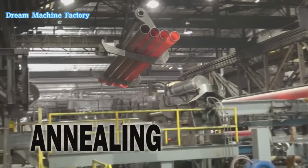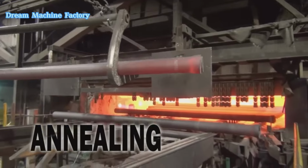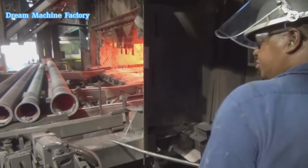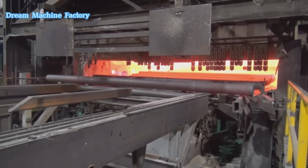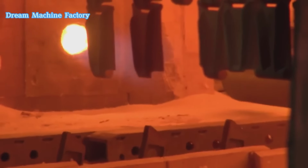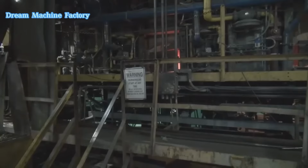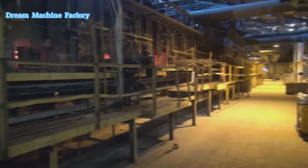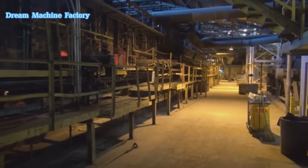Annealing is a critical heat treatment process that enhances the ductility, strength, and toughness of ductile iron pipes. After casting, the pipes are still brittle due to rapid cooling in the mold. To correct this, they are transferred to a natural gas-fired annealing oven, where temperatures reach 1,750 degrees Fahrenheit at the entry point. As the pipes move slowly through the furnace, the temperature gradually decreases to 1,350 degrees Fahrenheit in the cooling zone over 35 to 45 minutes.